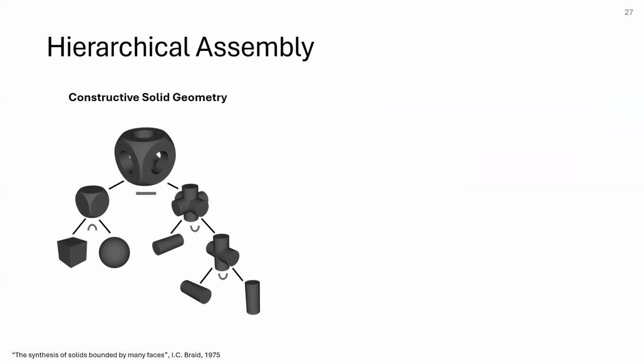And the way that Pasko did was to pull back on another piece of early computer geometry, and that's constructive solid geometry. So this was originally proposed in 1975. The idea is to take a pretty complicated geometric object, break it down into a binary tree-like structure until we have these component leaf nodes that describe some kind of basic geometry. So a cuboid, a sphere, a cylinder. Then we can translate, rotate, union, difference, intersect, whatever we need to build our composite object.